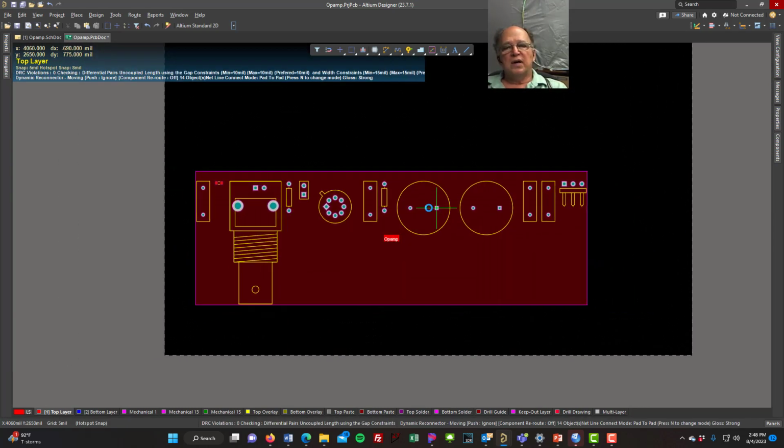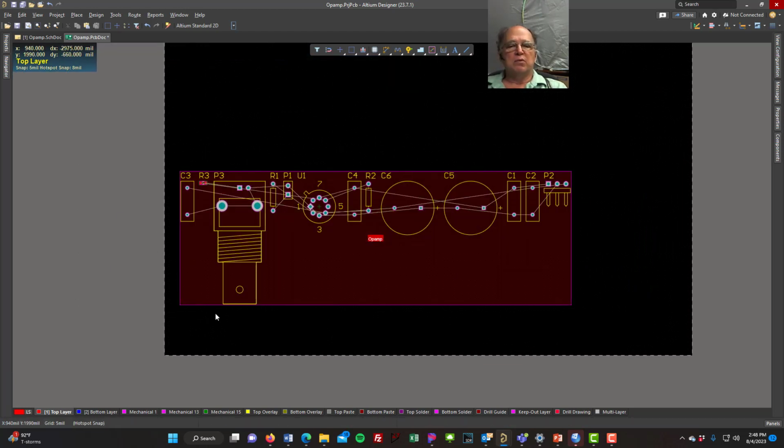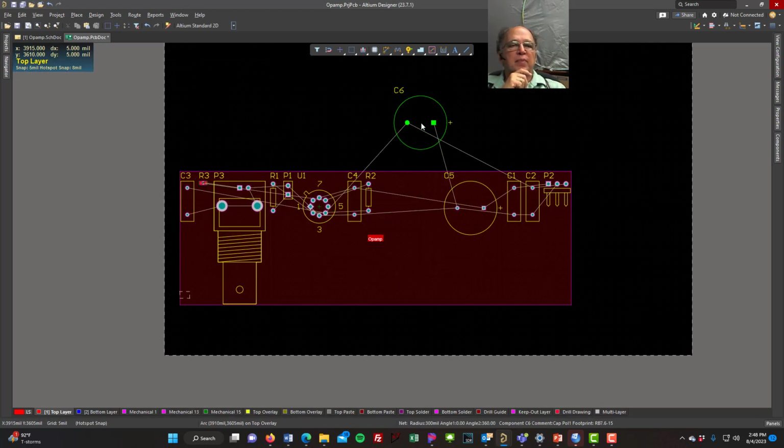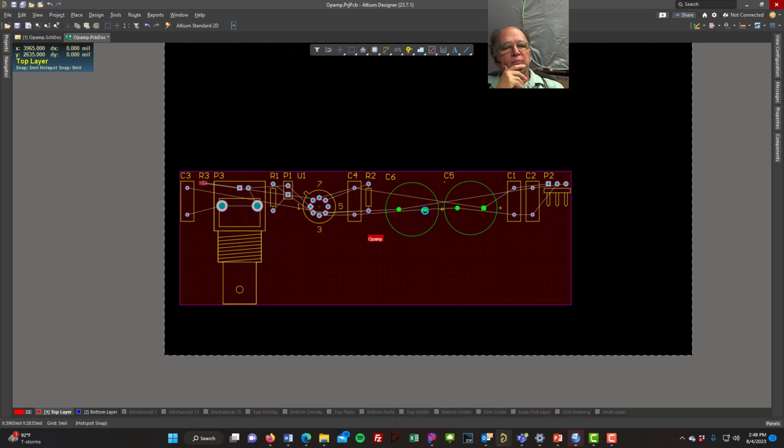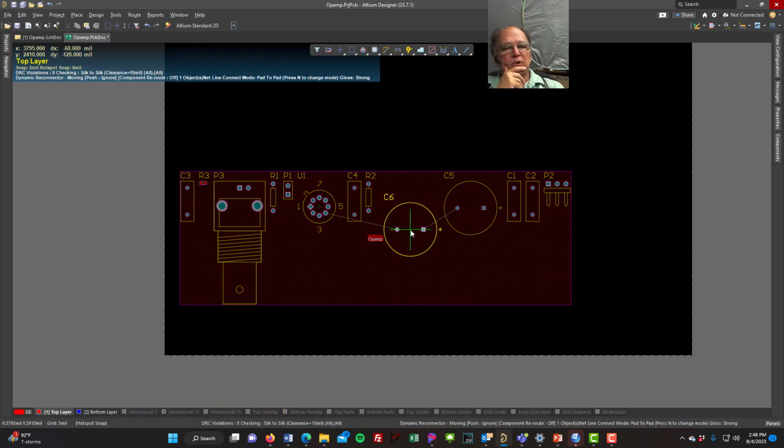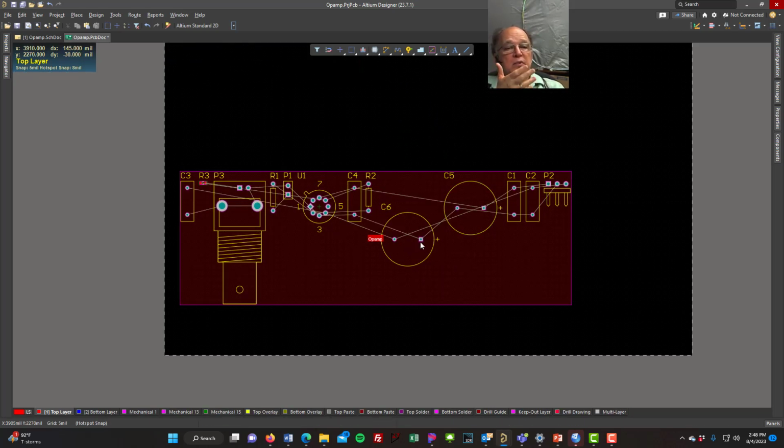And they're all inside this room. This magenta colored box is the room. So all my parts that were on that sheet went into one room, and here they are. Now if I take a part out of the room, see it turn green. Green is Altium's way of saying there's a problem. Turns green. Put the part back in the room. I got them too close there. And it's yellow. Right, if I did this, they overlap, they're green, they're too close. So that's what it's telling me.